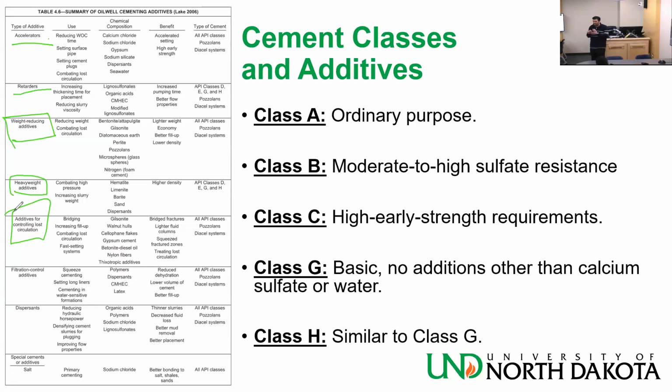Bentonite, because it builds like a filter cake around the hole. Bentonite diesel oil, so it is here. It helps build the mud cake around the well, a thick filter that prevents fluid from escaping. That's what it's used for. Because lost circulation means that your cement is escaping through the formation. Okay, you want to prevent that. You use bentonite, it creates a thin layer on those walls. And yeah, it works with the mud and the cement as well.